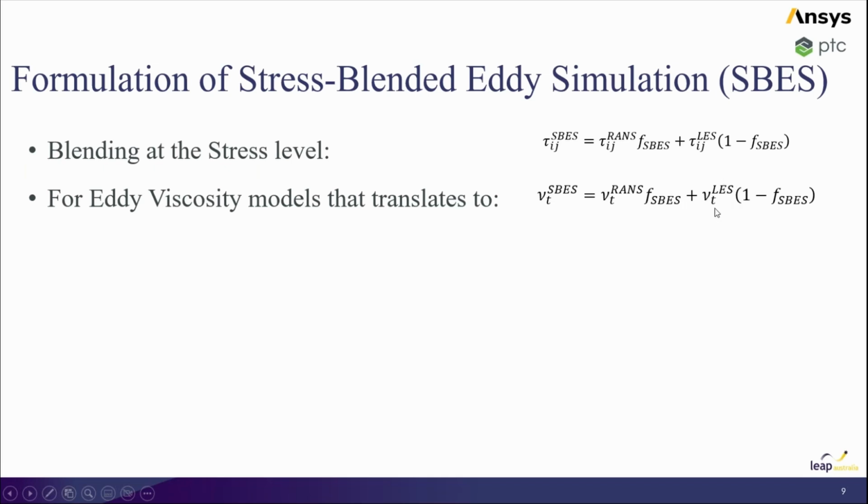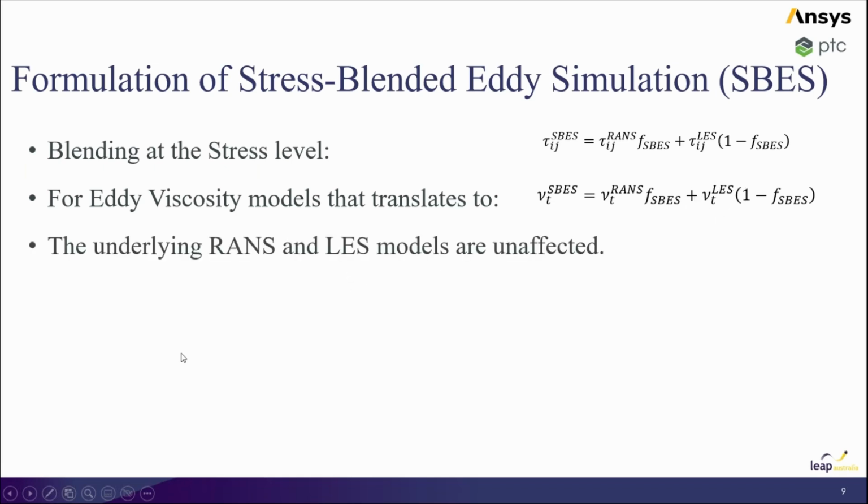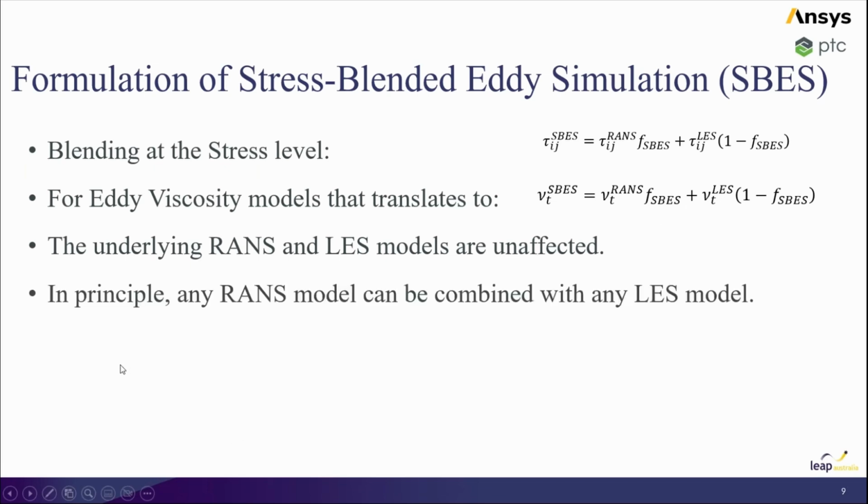Viscous term, essentially the damping there, that's representing that damping effect. But we don't change anything else. We don't change anything in RANS. We don't change anything in LES. And we just blend them together. So we can combine any RANS model with any LES model we want.